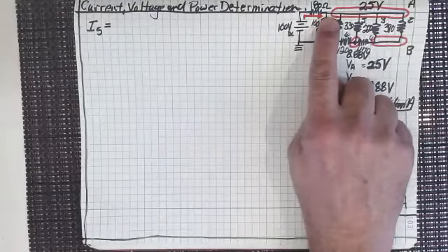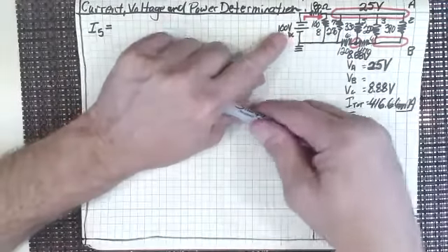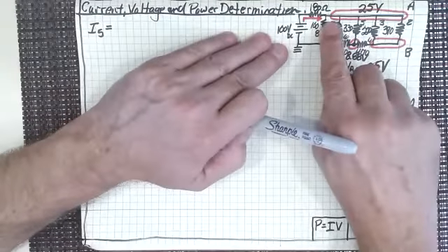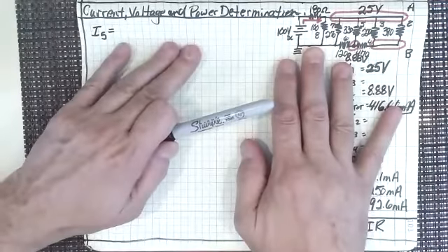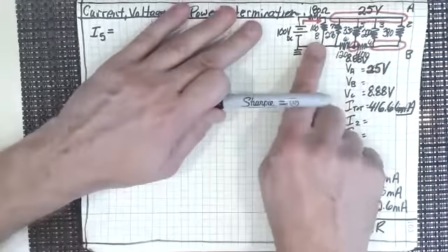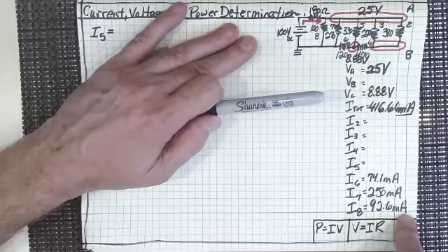So that's the total that's flowing into this point right here, that first junction, that first node that we have, isn't it? So the current is now going to be splitting up, and the current that's going on is going to be less. So let's look at that. We now know that the current in that first one, the 100 ohm resistor, that's I sub 8, is 92.6 milliamps.